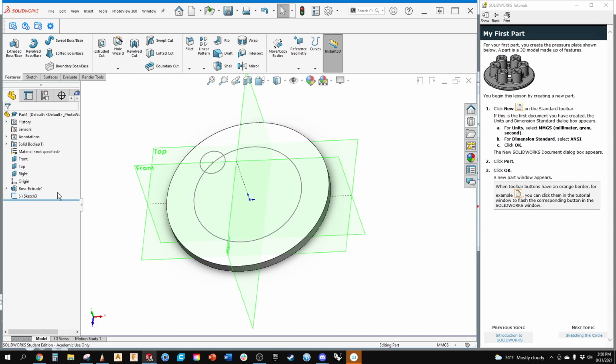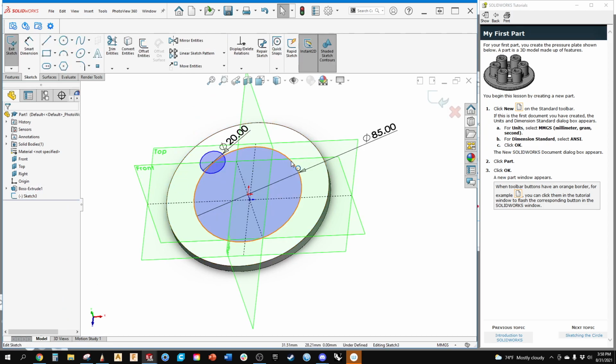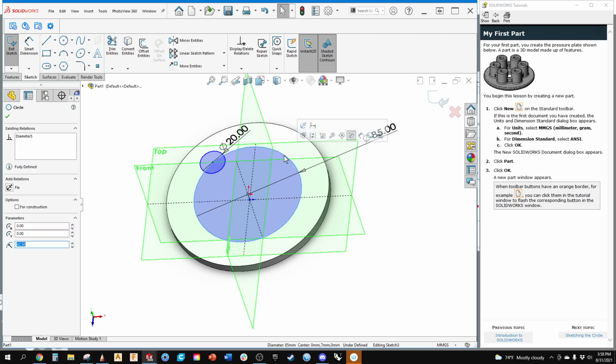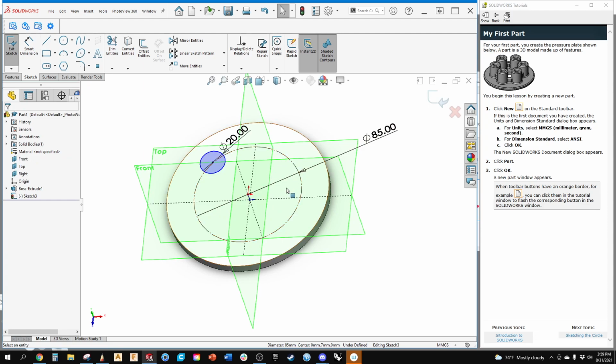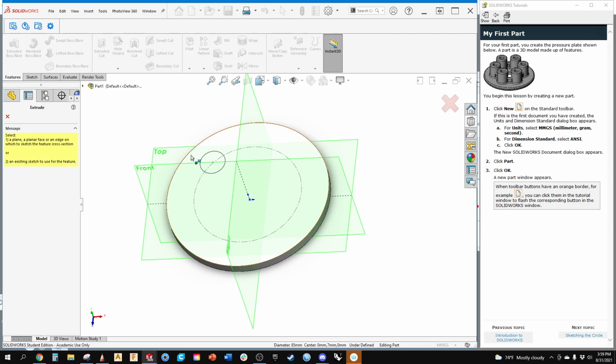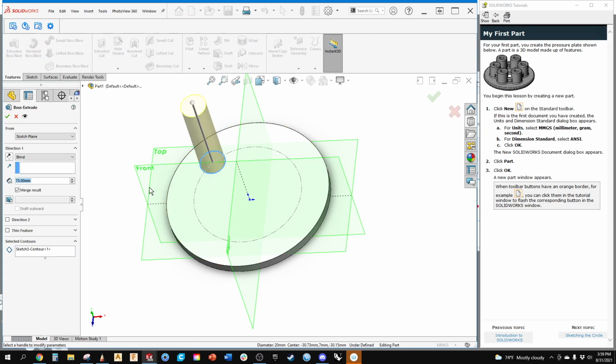If you don't want to take that approach, what we can do is we can take that sketch or that line and change it to construction geometry. What that means is it is a dashed line, and what that represents is just a reference point. You can snap to it, all that, but it won't extrude it. So if I make that a reference geometry, and then I go to extrude it, it will only extrude that item, nothing else in the sketch.